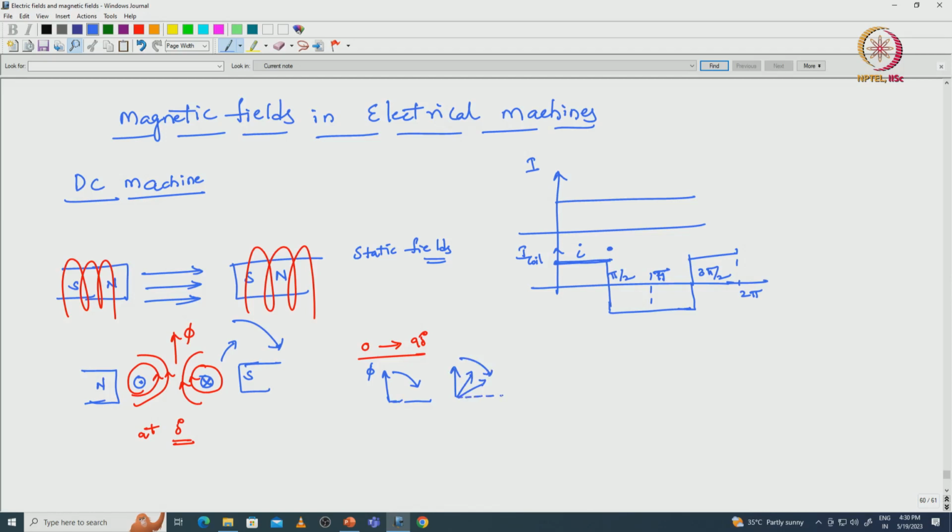At exactly 90 degrees, what will happen, we are changing the excitation, right, the current direction we are changing. The coil will be in this manner, earlier dot and cross before changing the current, here dot and here cross, the flux is in this direction, okay. We can find that with the thumb rule. Dot means anti-clockwise, cross means clockwise direction.